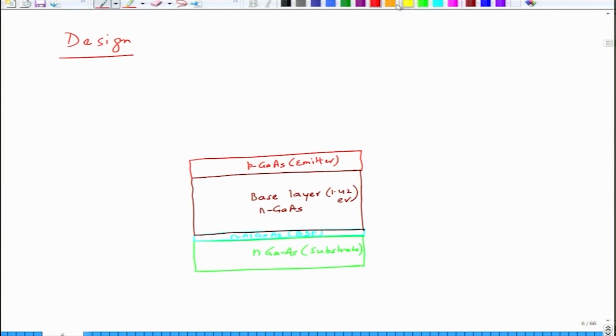and then we have on top again a small layer of P type GaAs, which is called a window. Okay. But again it reduces the surface recombination. And then we have on top a layer of zinc sulphide and magnesium difluoride, which is ARC essentially. Okay. So, you can say it is ARC.